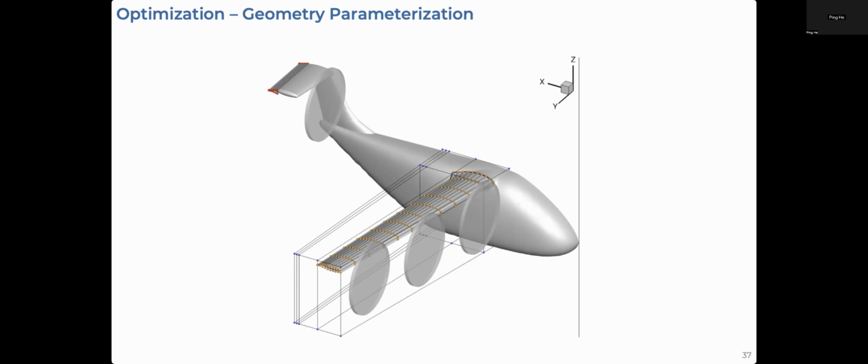Something to highlight is that the structural sizing of the wing reaches roughly the minimum bound for nearly all of the structural panels, apart from a few near the root, which of course makes sense because these are the ones that have the largest force. On the other hand, the tail remains quite large even though it doesn't reach failure. What is interesting about this is we have a panel that actually reaches 70 millimeters, which is extremely thick for a carbon composite laminate that we're using.